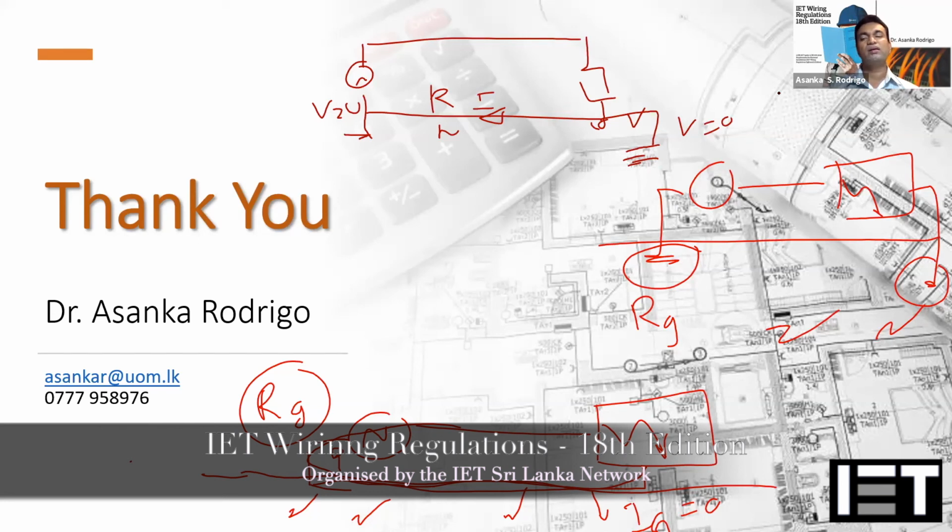Even when you go with the bulk supply, you can decide whether to run the generator as a TN earthing system. Sometimes in some locations you have to run the standby generator as an emergency standby, where even if something happens you don't want to stop the generator. In that case, even with the TN system, you can run your generator as an IT system. That is also allowed, especially for data centers and many other special installations, where we design like that. Your normal system runs as a TN system, and under the emergency situation you run your emergency supply as an IT system, so that even with any other disturbances, the system keeps running. So my opinion is, if you have your dedicated transformer, why do you want to run it as TT? Go for TN.